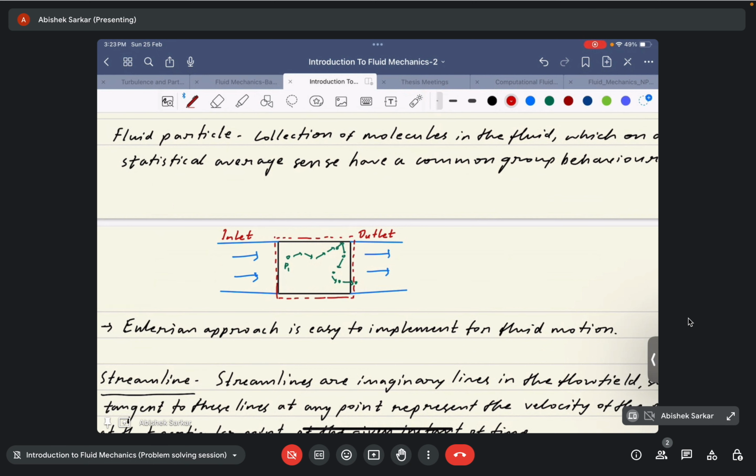And for understanding how the flow parameters change at the outlet because of the flow of the incoming stream through this duct, the only thing that we need to know a priori to get the final results is the initial profile of the fluid flow that is approaching the duct. So that is a simple parabolic profile. It's just an assumption, okay?